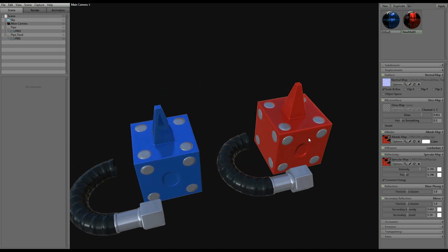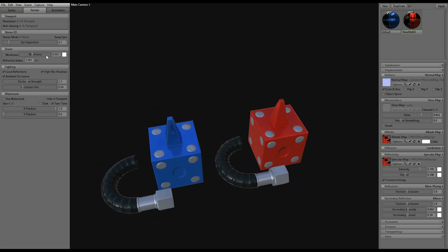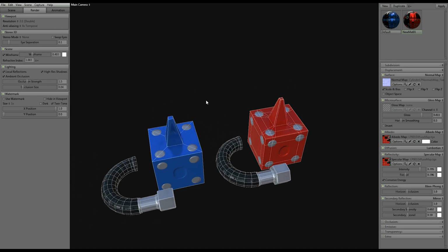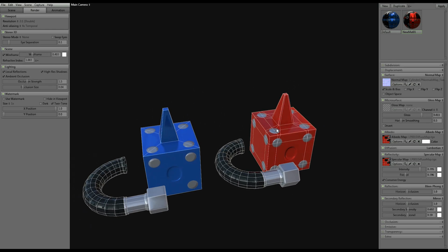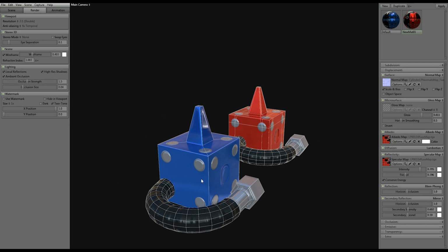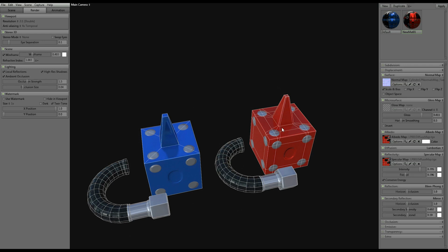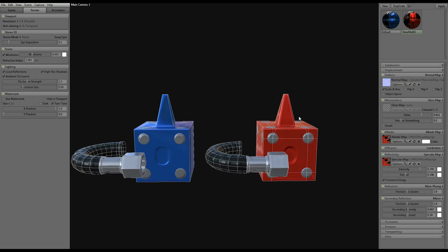So how did I fix this? Let me turn on my wireframe on the edges, and you can see what's going on on the low poly, how I went ahead and fixed this stuff. With this one here, it's the traditional box modeling edges and topology. But with this one, I actually added supporting edges. And in addition to that, I inserted vertices, or I have a cross section here with vertices right in the middle of where that high poly floating geometry was sitting.